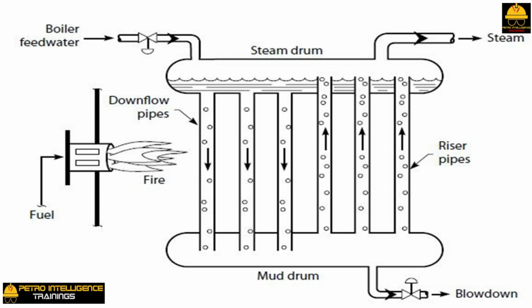A certain amount of water is drained from the mud drum. The amount of this blowdown is determined by measuring the TDS in the steam drum. Typically, a target of several thousand parts per million, ppm, of TDS is specified. If the steam is generated at a low pressure, 150 psig, for use in reboilers, rather high TDS may be acceptable. If the steam is generated at a high pressure, 1400 psig, for use in high-speed turbines, a much lower TDS target would be set.